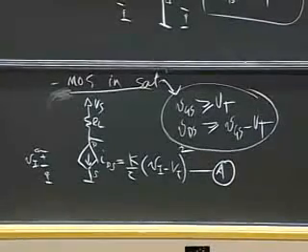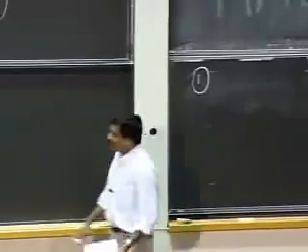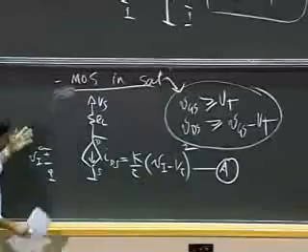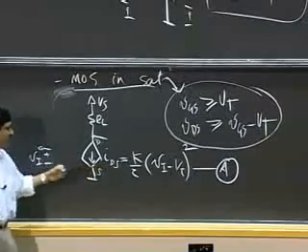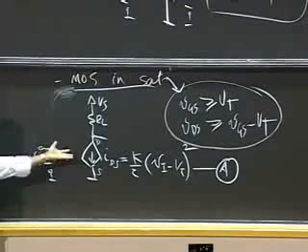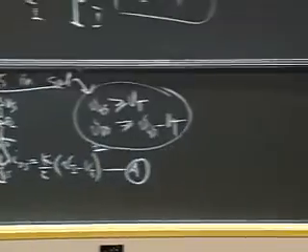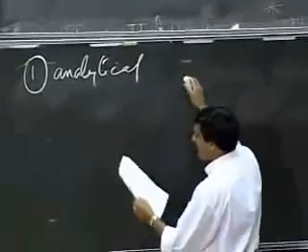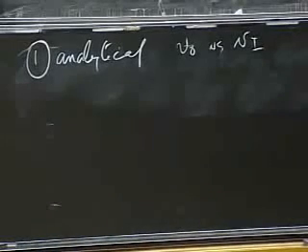So with this new little circuit with the MOSFET working as a current source, let's go ahead and analyze our amplifier. So notice that to analyze this circuit, I have a current source. It's a dependent current source where the current depends on the square of the input. Okay, so I want to go and analyze it. So this is a nonlinear circuit. Okay, so I can apply any one of the methods that we talked about last week for nonlinear circuits. So to analyze it, I'll go ahead and use the analytical method.